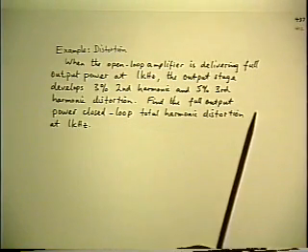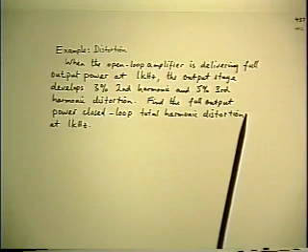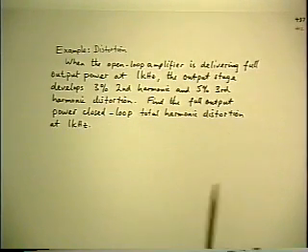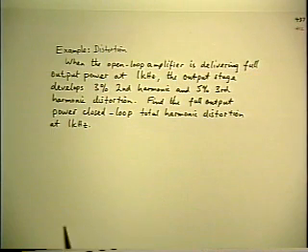This is where we're going to use that. You have to know where you start. That is, how much distortion is actually generated in the power output stage. That's where most of it comes from, because that's where the signal amplitude is largest, and therefore the nonlinearity of the characteristic is worst, because you're exercising the operating point over essentially the full range.